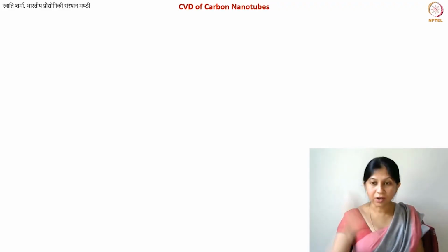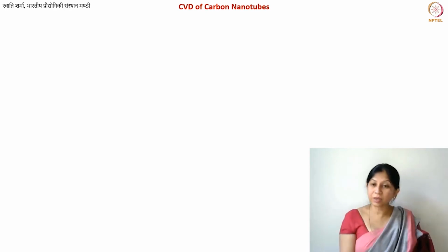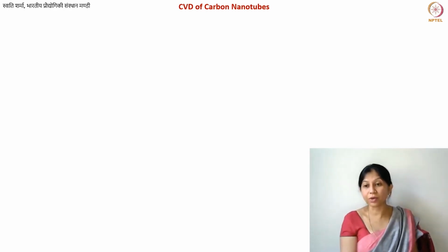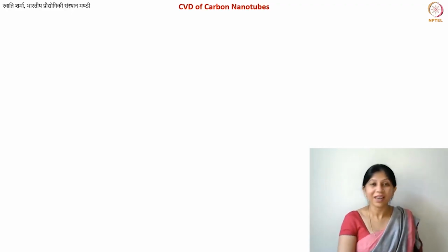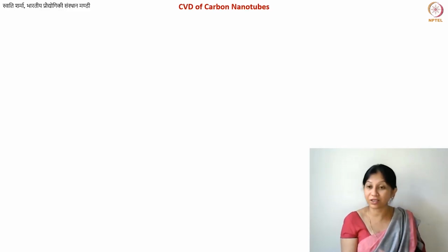Right, so now let us talk about the fabrication processes for carbon nanotubes. You can again call them synthesis or fabrication as you like, or manufacturing. The idea is, you know that for making carbon materials, especially nanoscale carbon materials, if you want to do that at a larger scale, the most cost-effective technique is chemical vapor deposition. This is the same thing also when you are working with graphene or other various carbon materials. Maybe we learn also about diamond-like carbon and so on.